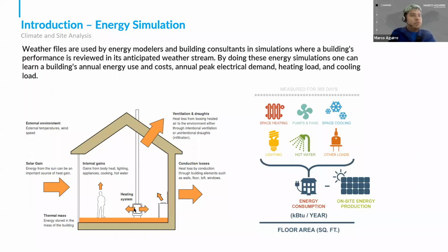Depending on our system selections, we'll also see energy consumption coming from other areas like equipment, lighting, hot water, pumps, fans. All of this is based on what your climate condition is. So you can assume if you are in a location that has more extreme winters, you're going to see an increase in heating, and with more severe summers, an increase in cooling. And if you can take advantage of your location's climate conditions and some of the passive strategies that we're going to go through next, that can be a way for us to reduce our energy consumption.